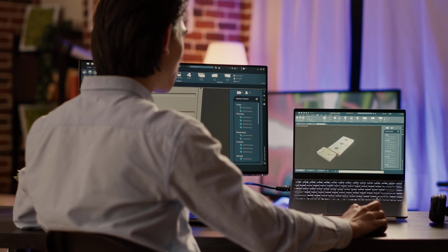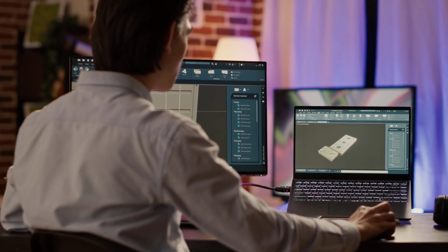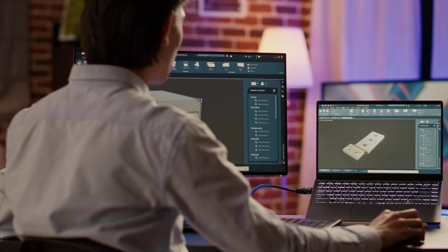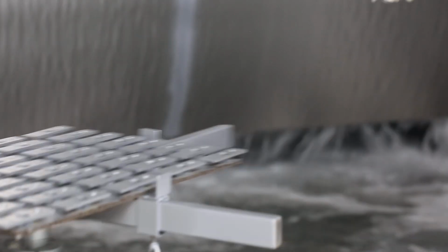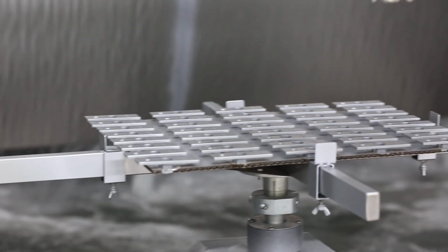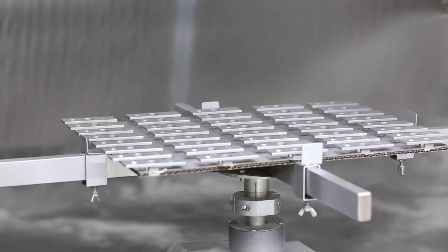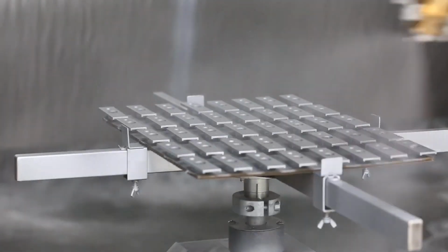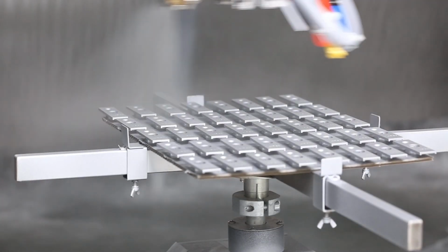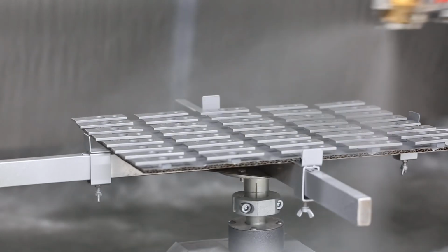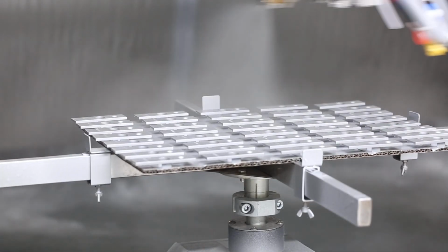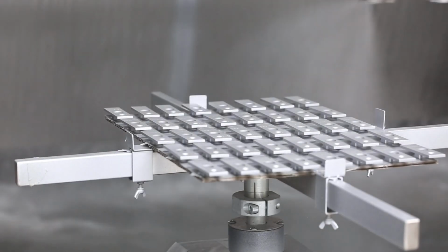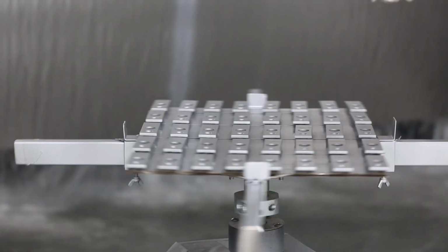Now that we agree on our terms, how do they apply to your product development goals? Well, many designers erroneously believe that very tight tolerances and very high accuracy are always synonymous with good or high quality. And because everyone naturally wants a good product, designers therefore automatically specify tight tolerances in their design drawings, even for features that don't require it, in the belief this will yield the magical and mysterious characteristic we call quality.